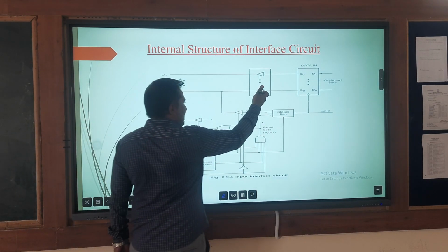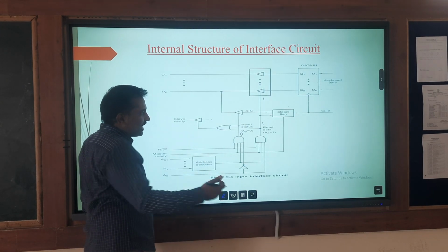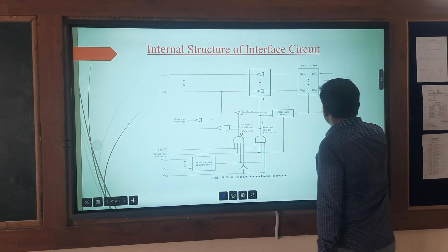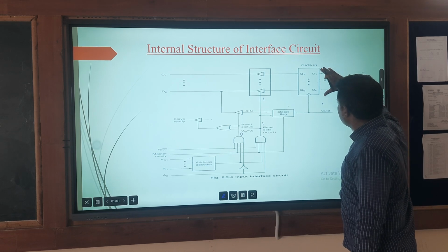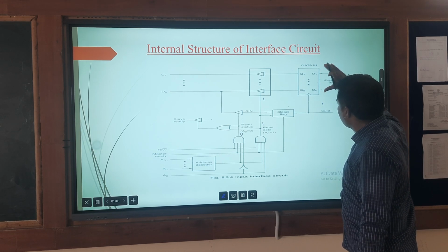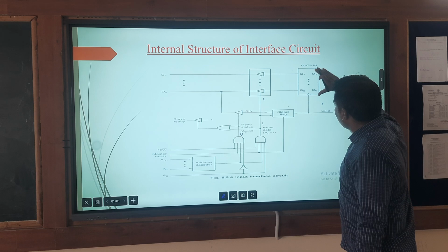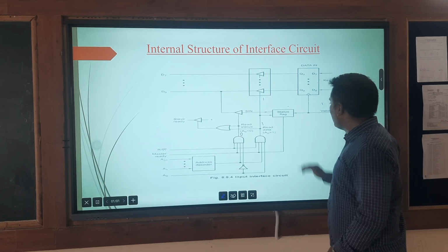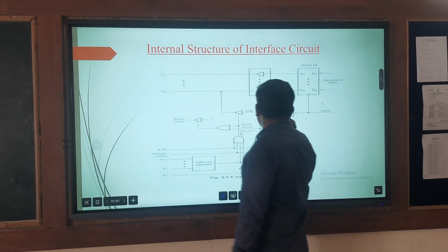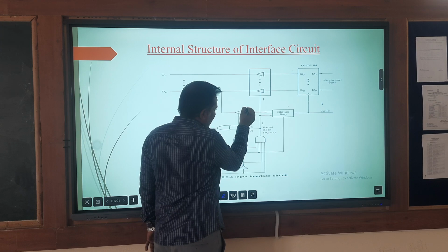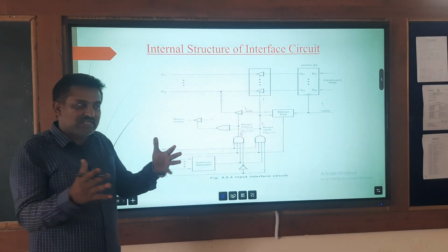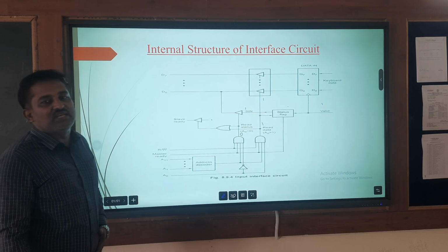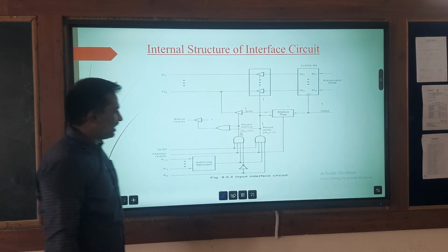It will be used as an enable signal, so that whenever the valid signal is equal to 1, the data present in the data in buffer register in the interface circuit is valid data, which sets the status flag. When status flag SIN is equal to 1, that indicates there is data present in the data in buffer register.